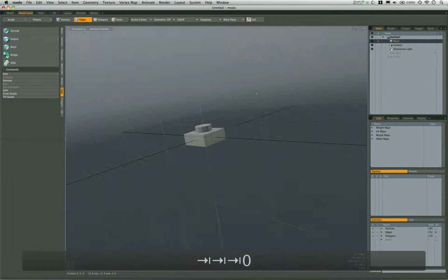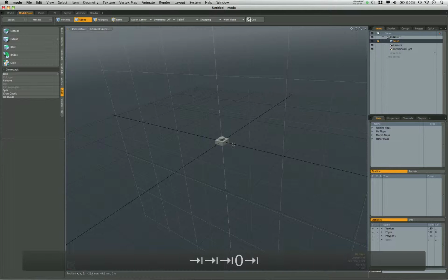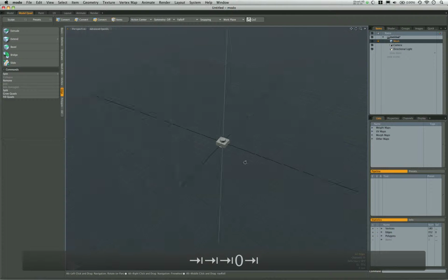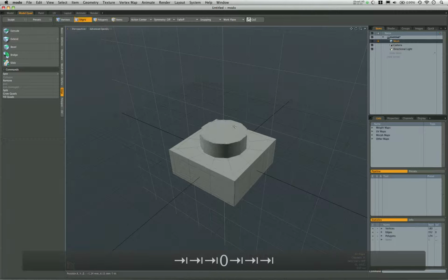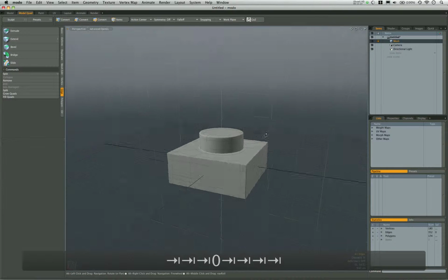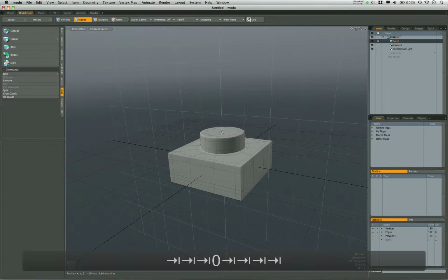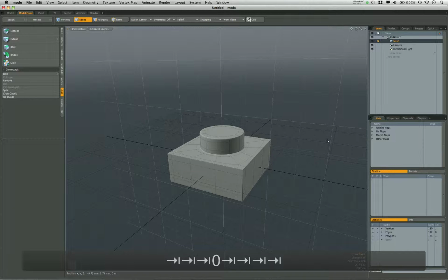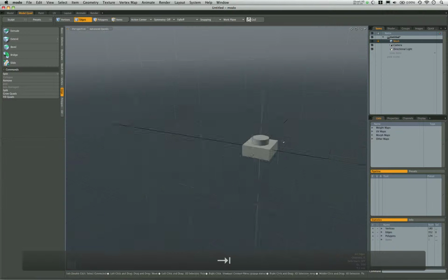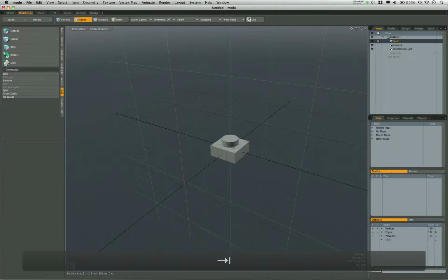Okay, and like I said, if we're out here, being out of sub D is not gonna hurt us at all. Once we get in and closer, obviously we'll want sub D on. But if we're using adaptive subdivision, that will clear up a lot of that manually. Or if we're really short on render resources, we can always unsubdivide them entirely. We're going to get a pretty decent surface anyway.